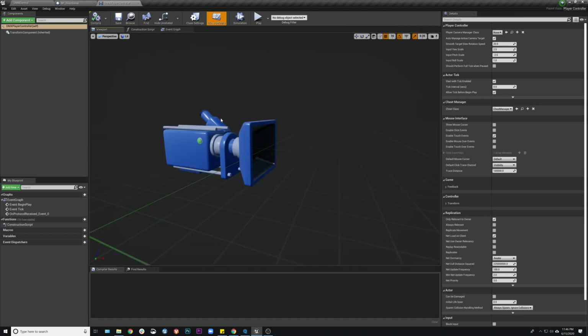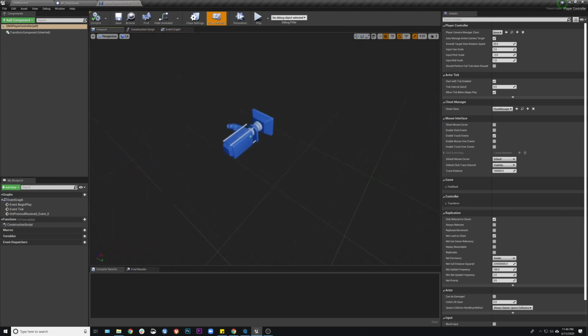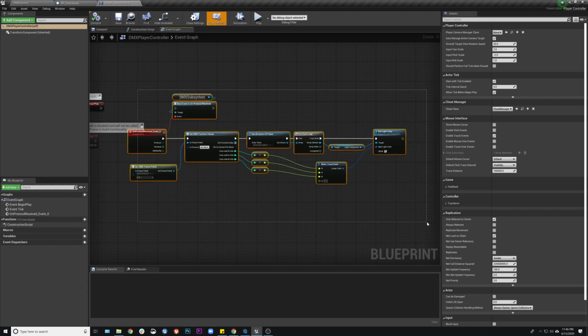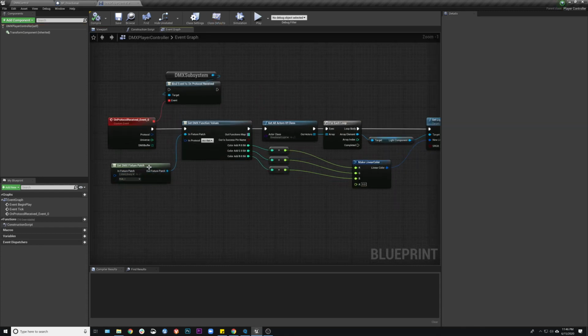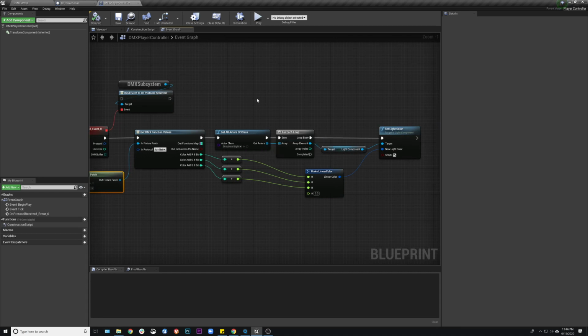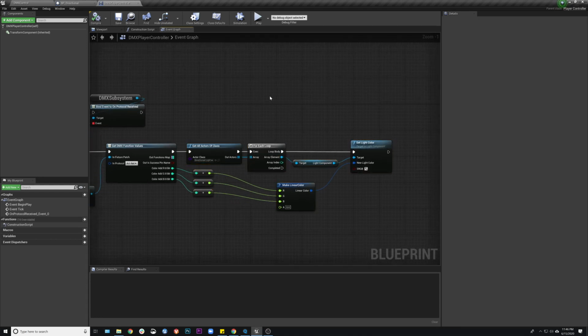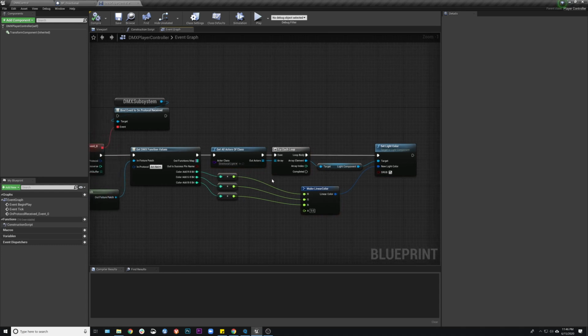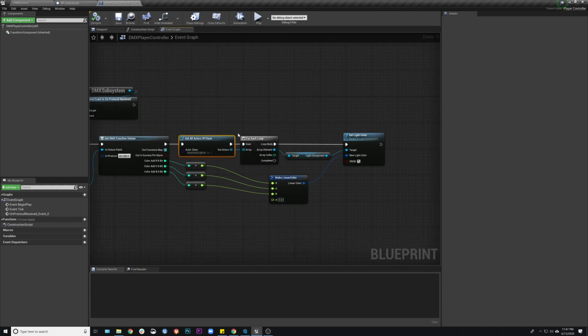So the view inside the viewport, it's literally just a camera. That's the only thing that's actually visible. But here's kind of what I set up, and literally this is just the exact same thing. In this case, I specified exactly which fixture I wanted. So I said listen library RGB1, and then now I'm going to use a different method to get what I'm looking for. So instead of actually hard referencing the directional light or some other actor, I'm actually going to use a get all actors of class. So I'm going to try and get every directional light in the scene.